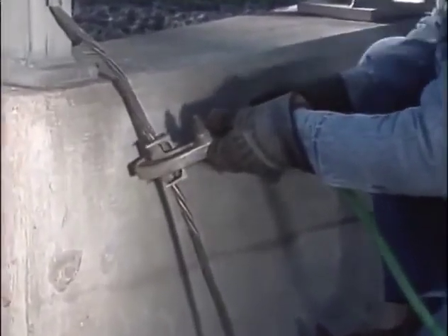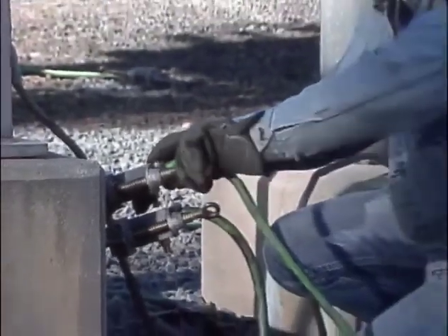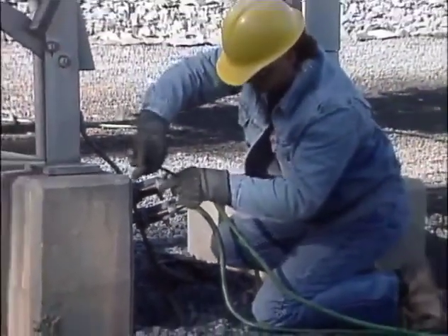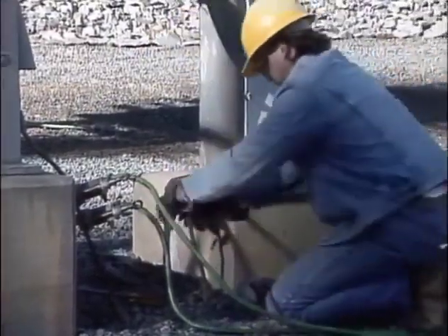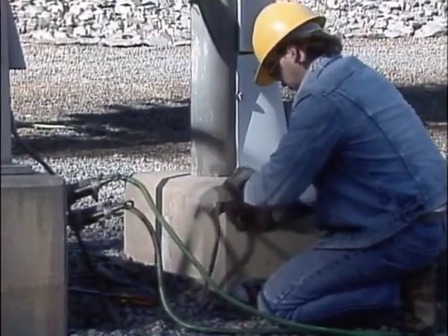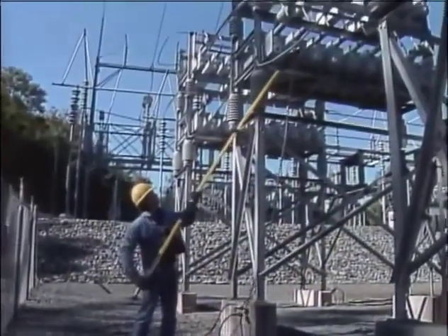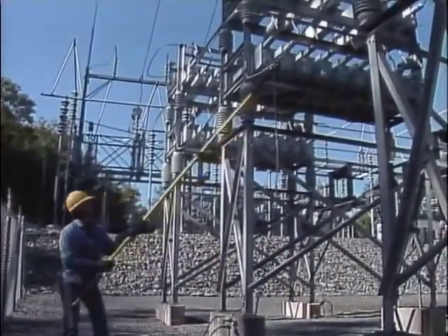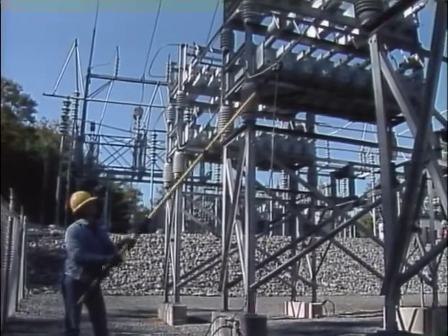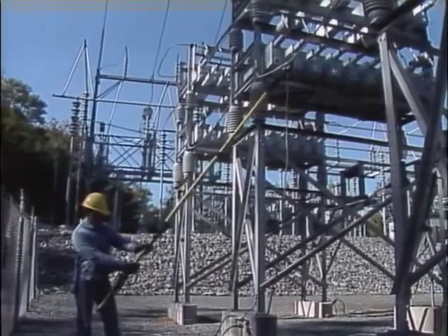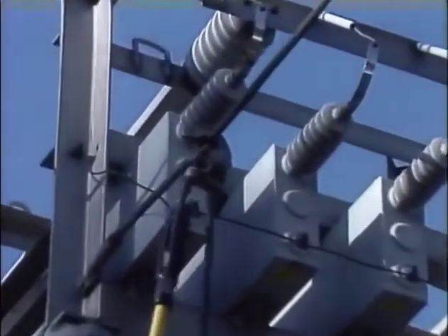This worker makes a habit of connecting all of the portable grounds that he'll use to ground the bank to station ground before making any other connections. That way, when he connects a portable ground to the bank, he knows the other end is connected to an established ground. After making the connection to an established ground, the next connection is usually to the neutral of the capacitor bank. For this bank, the neutrals for the lower tiers can be grounded by attaching the portable ground to one of the conductors that connects the frames together. The neutrals for the upper tiers of capacitors are grounded the same way.